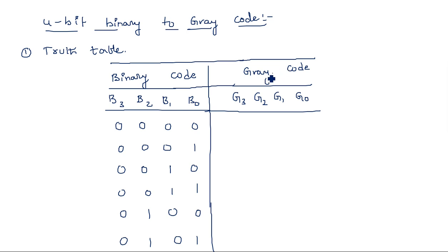So for that, it is also known as a mirror image code. Mirror image code representation is very easy. First you need to take 0 1 here. After that, take a mirror image of this one, so it becomes 1 0 here. Now append zeros here and append ones here. Next, take the mirror image for these two. So it is 1 0, it is 1 1, and next we have 0 1 0 0, 0 1 0 0.